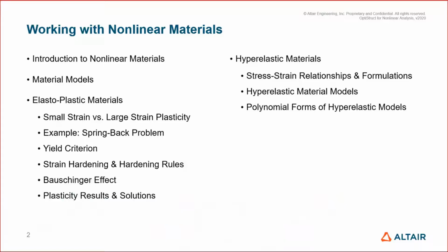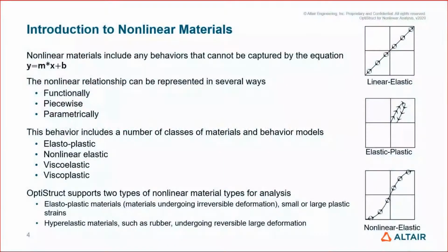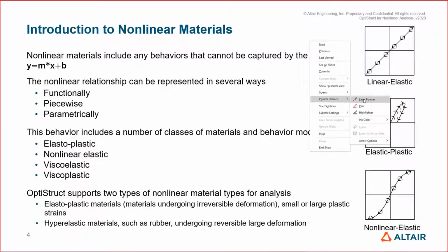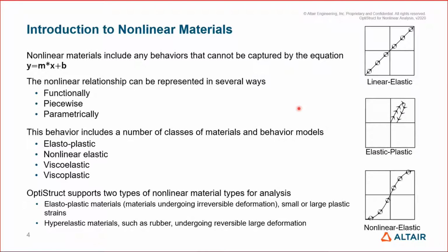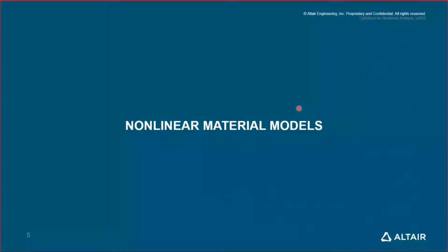Nonlinear materials. So for nonlinear materials, I think it's pretty clear where we actually need to use it, right? When your material is behaving in the plastic region, or you expect deformation in the plastic region, then you definitely need to use nonlinear materials.